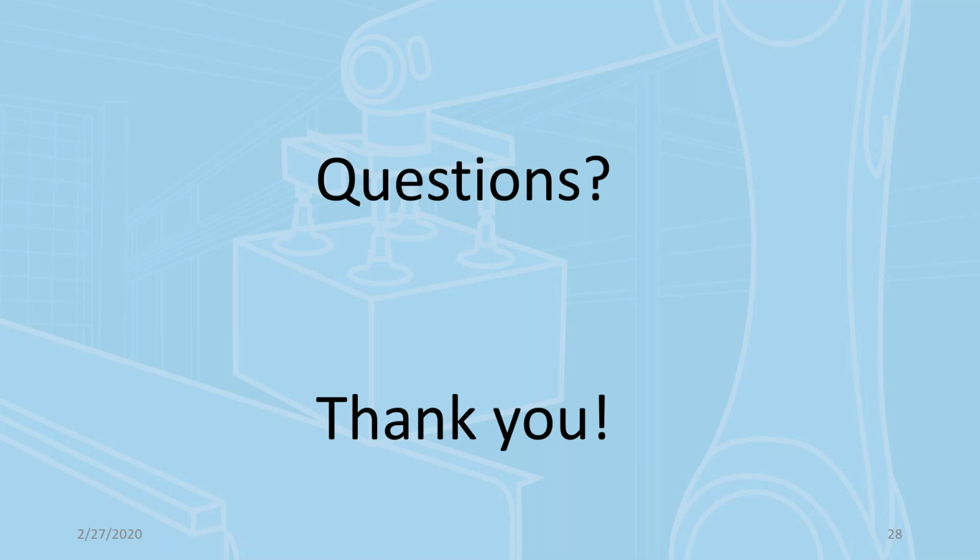You do still have to consider the other implementation costs, and I think despite what the cobot manufacturers say about ease of use and that you don't need as much in terms of safety cages and light curtains and other things around the robot, you're still looking at least a 2x or a 3x factor once it's all installed and programmed and ready to run.